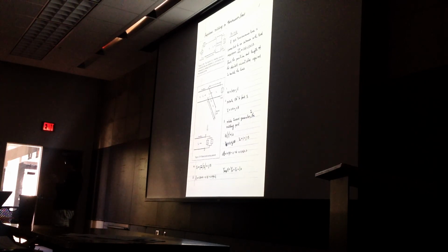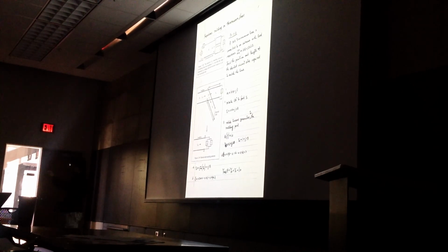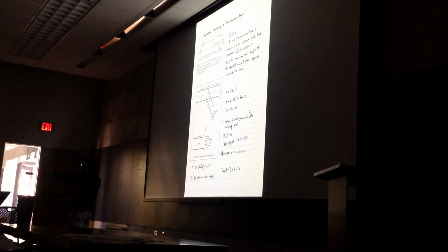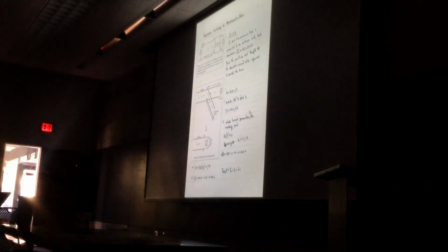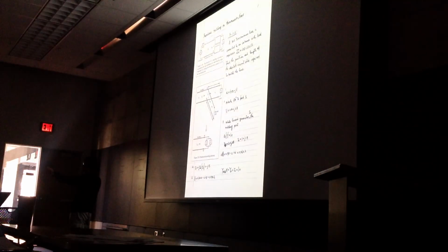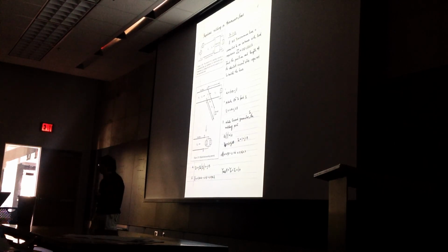Second, even if it really is 10 to the minus 8 Henry at 1 gigahertz, at 1.1 gigahertz it can be different. But using this as a transmission line, if the coaxial cable is a high quality coaxial cable, it's always a TEM wave. So the impedance will be 50 ohm and the speed of light is still fairly constant. So it's much more controllable.